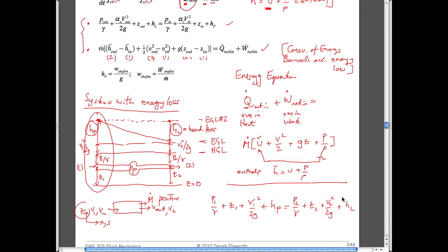Okay, well, the other thing is that this right-hand term here, of course, now is this. When you think about it, it's no more than that. And so what it is that we've now defined Bernoulli. We have the ability to put energy into the system in terms of a pump in some way, and we have the ability to have energy losses accommodated within the system, say to friction along pipes or friction in porous media, for instance, by these terms, which are merely defined in terms of length. They have to be adding apples and apples, so these have to be the same units as the other components.